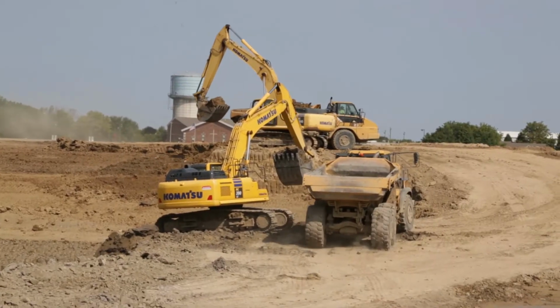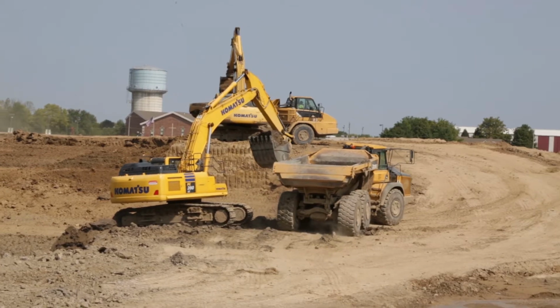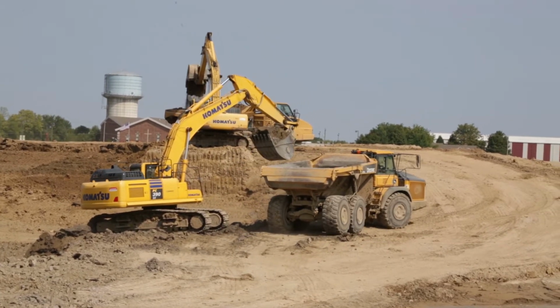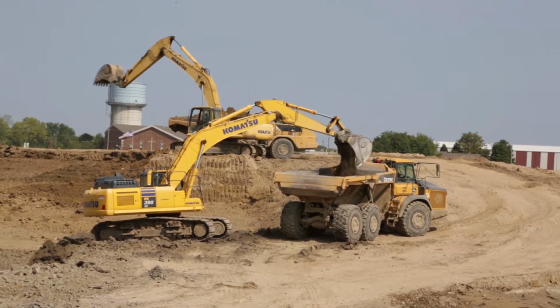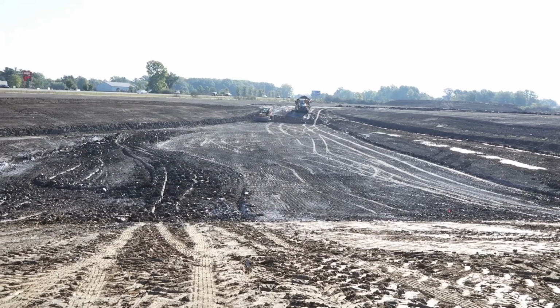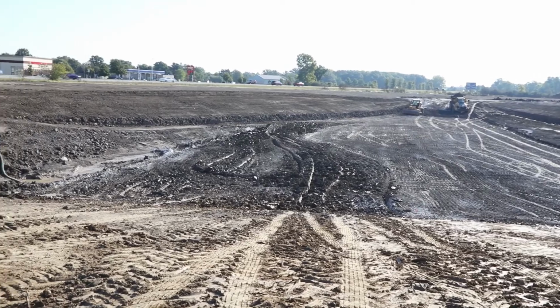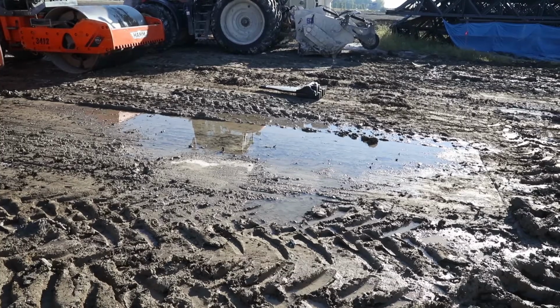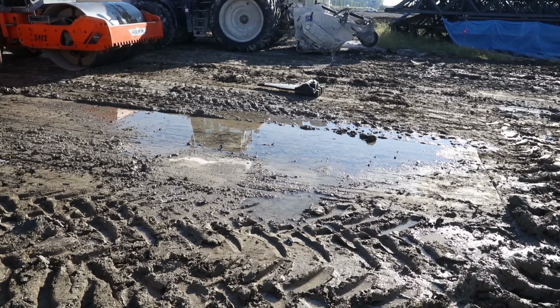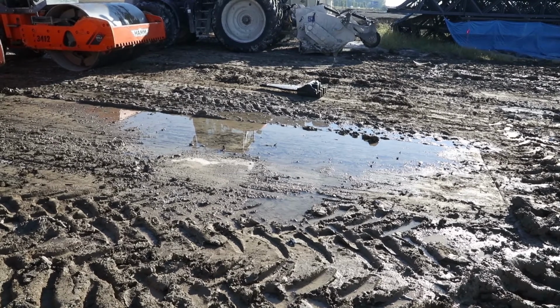As land-disturbing activities occur on an active construction site, bare soils and unvegetated areas are exposed to erosive forces. Stabilizing these areas as soon as possible helps to keep soils in place, preventing erosion as well as sediment from moving. It also helps to reduce the amount of accumulated sediment deposits and maintenance needed on other installed BMPs.